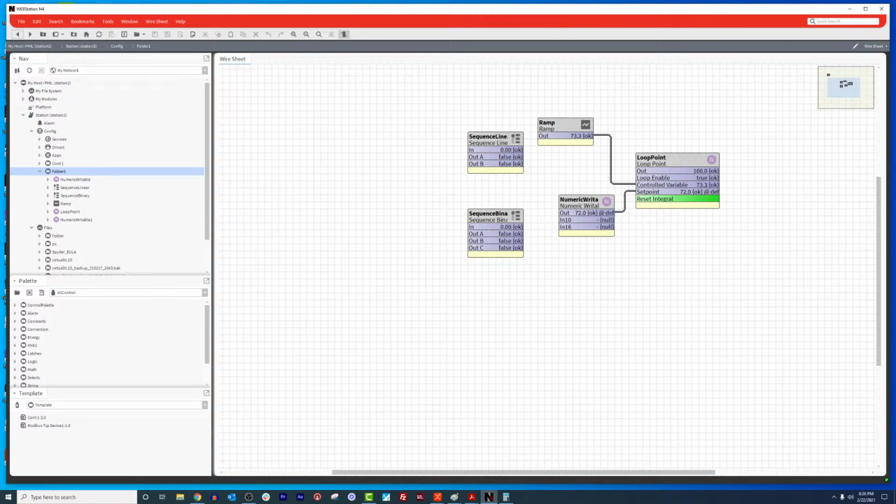Don't overthink it. Most of the time, if you're having an issue with your PID loops, your proportional band is off, your integral's off, or you got some sort of disruption to the process loop. You know, you got a valve that's leaking through or something. So you got to make sure your stuff's mechanically sound before you ever try to tune anything. But assuming everything's mechanically sound and you got your proportional band right, integral's pretty easy to tune.